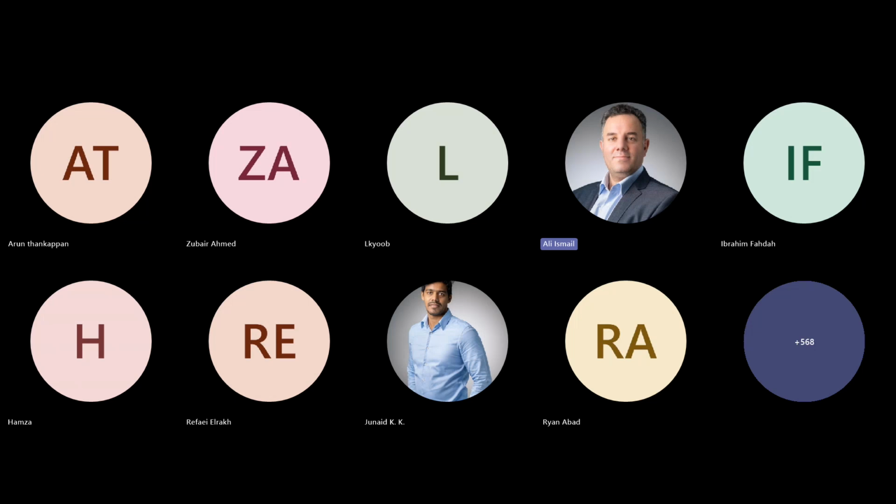For modeling walls, I think at the moment it is not necessary to have all finishing layers, because we are not checking any regulations related to the finishing layers. And we prefer the BIM model not to be very big for no added value. But if your model is already modeled with finishing layers, of course it does no harm, as long as you stay within the maximum file size limit.